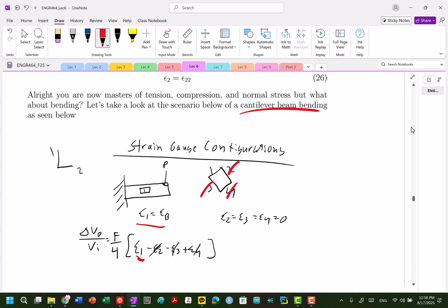Is the bending strain going to be positive or negative? And then what I do is, when we're doing bending, this is top. So if this line is solid, if it's dashed, that means it's on the bottom. So if I'm bending in this scenario, basically the beam is going to be elongating, right? So this strain of bending will indeed be positive. Now that's going to come out essentially in the wash, but important to kind of understand.